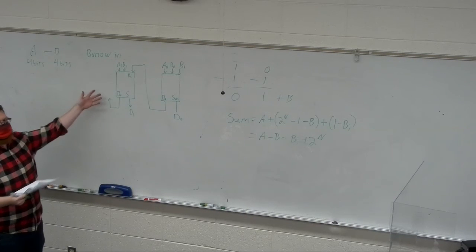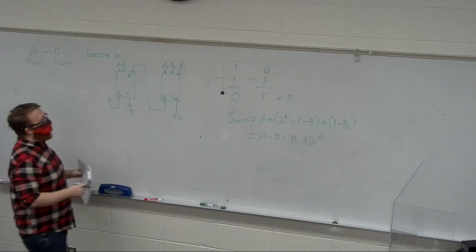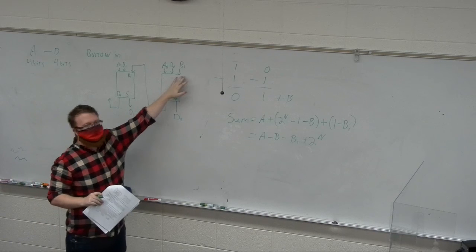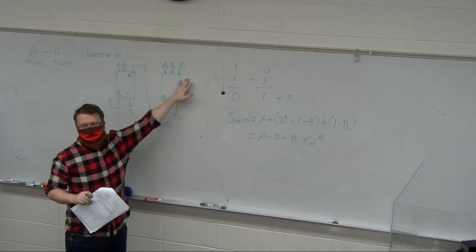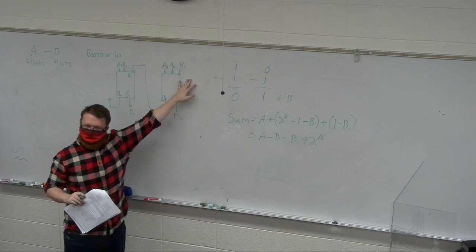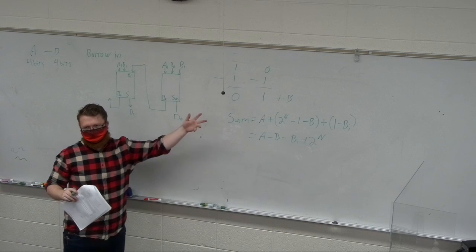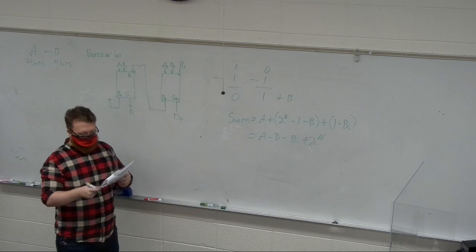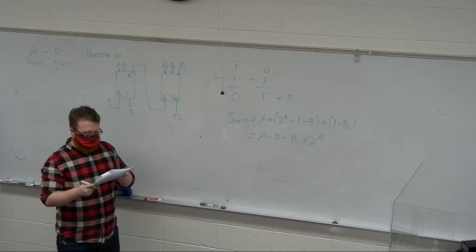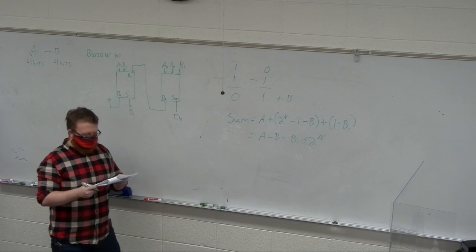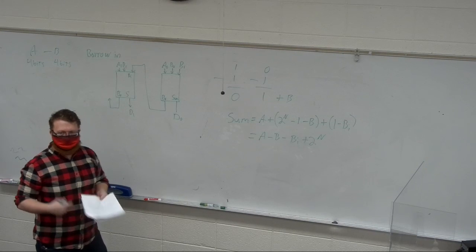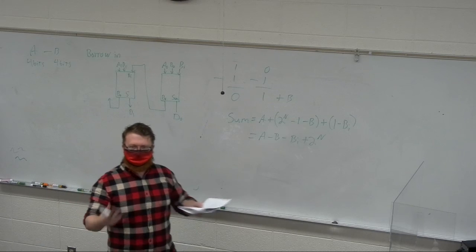Well, here's your logic. It's the same thing, right? The only difference is you don't have the luxury of using the half adder in the first circuit because you may need to borrow in. And that borrow in is going to tell you something useful, which is that if it ends up being a negative number in that first column. The truth table on figure 8-15 is probably the most straightforward way of understanding that, since we speak truth table, right?